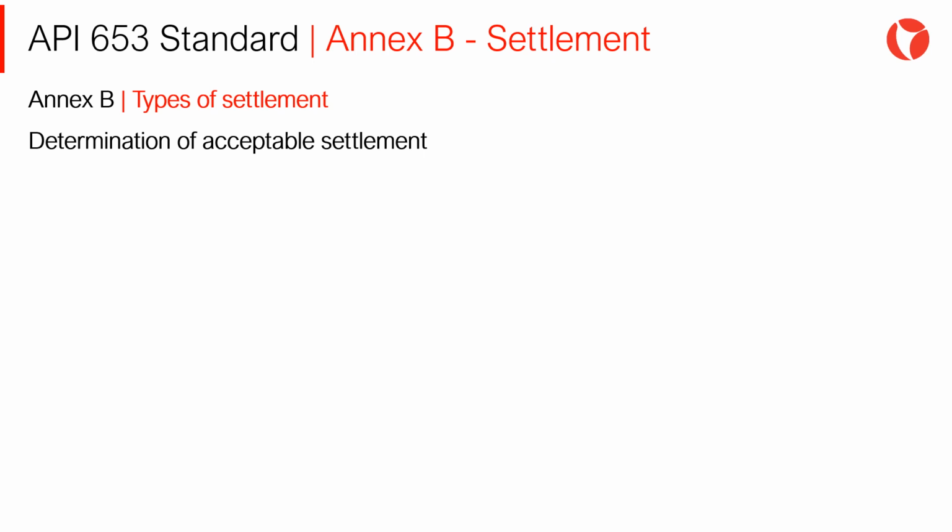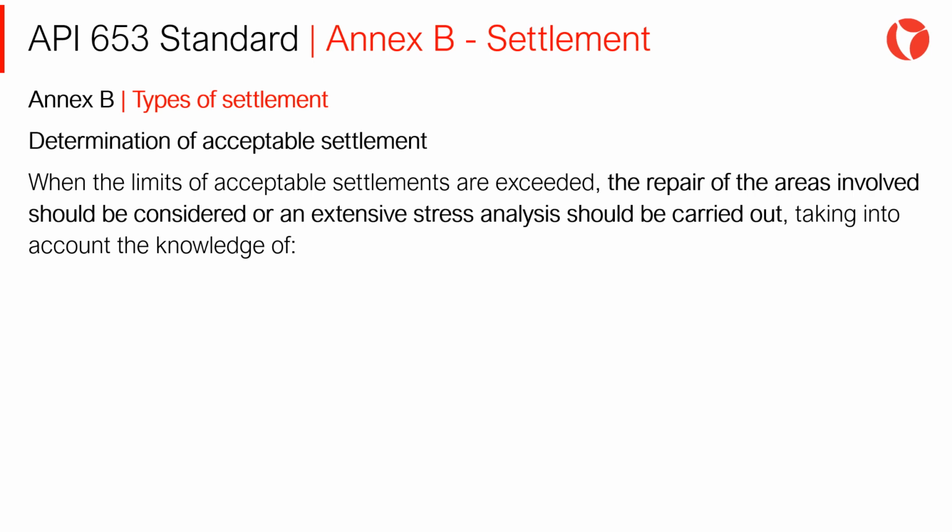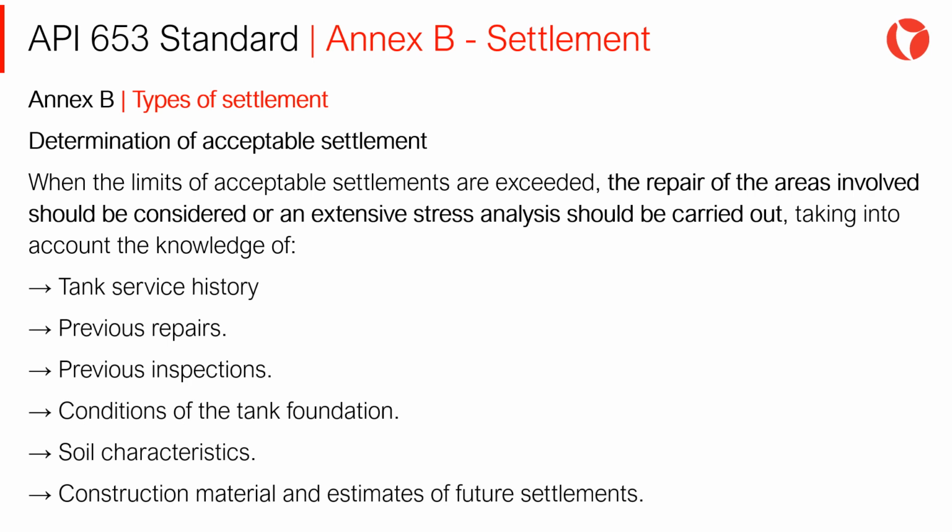The question at this point is the following: what is the acceptable settlement in a storage tank? The determination of an acceptable settlement is carried out according to what is stated in Annex B. When the limits of acceptable settlement are exceeded, the repair of the areas involved should be considered, or an extensive stress analysis should be carried out, taking into account the knowledge of the following: tank service history, previous repairs, previous inspections, conditions of the tank foundation, soil characteristics, construction material, and estimates of future settlements.